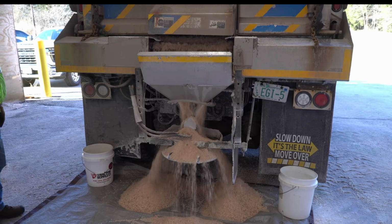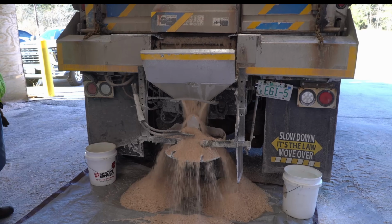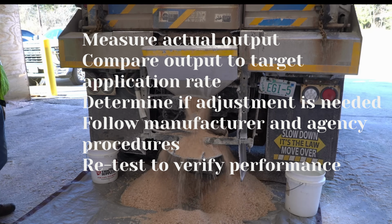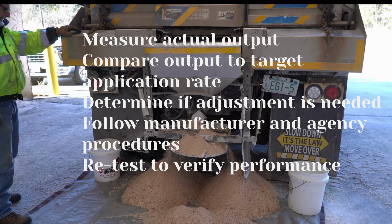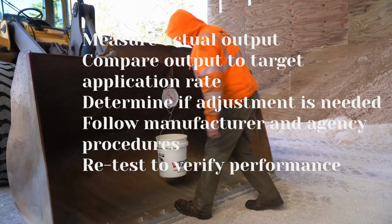Menus, terminology, adjustment methods, and access levels vary across manufacturers and controller systems. However, the general verification process remains similar. Measure actual output, compare actual output to target application rate, determine whether adjustment or maintenance may be needed, follow manufacturer and agency procedures, and retest to verify performance.